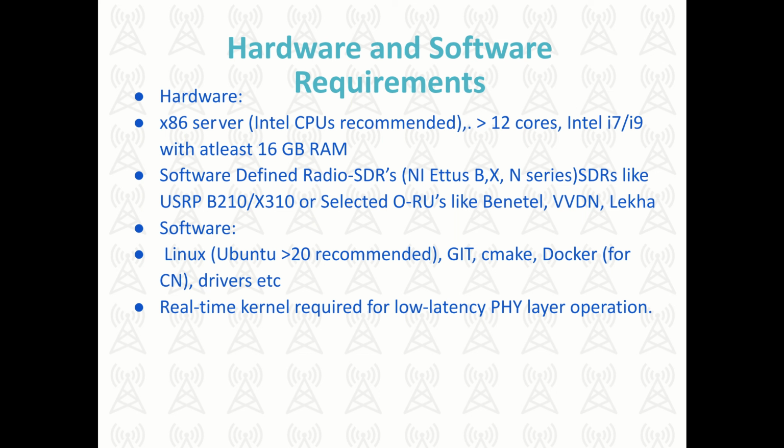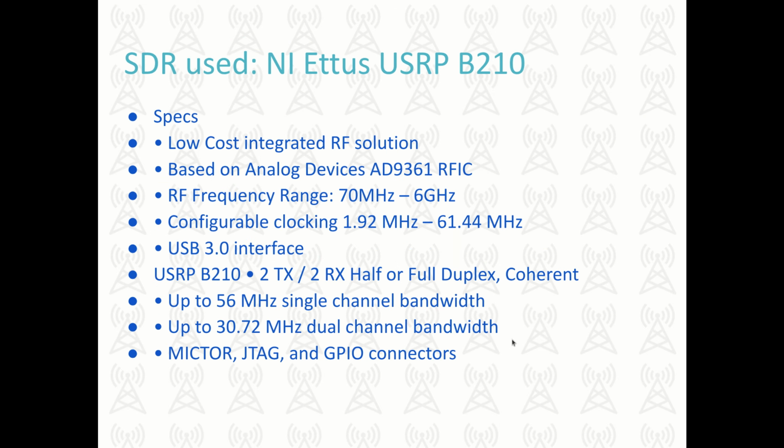Okay, so they only support the USRP family of SDRs, and then selected ORUs, which we already discussed: Benetel, VVDN and Lekha. Software is typically Ubuntu greater than 20. There are quite a few software tools and drivers. A real-time kernel is required for low latency PHY layer operation.